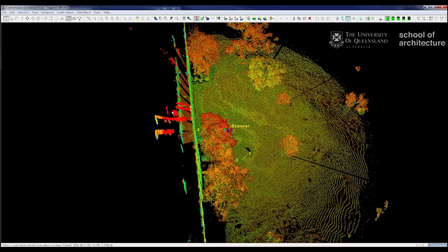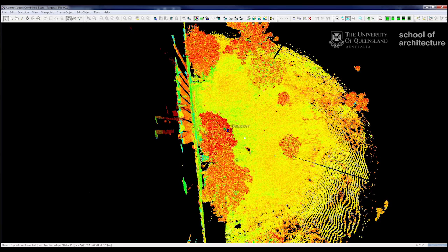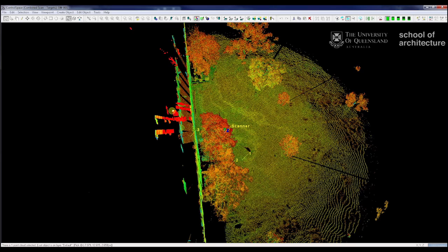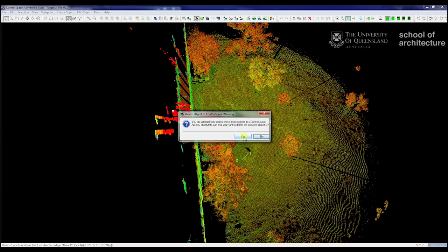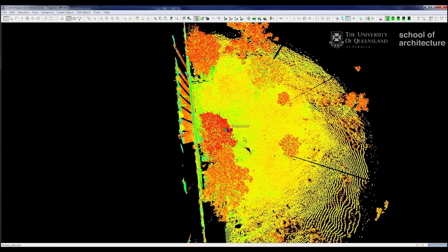This will have all the scan data that we do want, which is our edited scan, as well as that old scan. So we have to make sure we get in here and delete it, otherwise we're copying over two scans. So we just select that, then press delete, then press yes. There we go, we've done that.